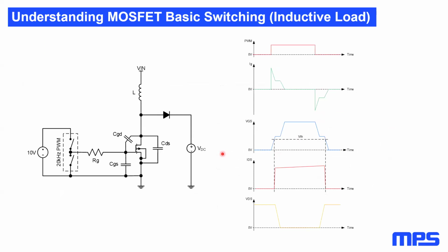The switching performance of the MOSFET transistor is determined by how quickly the voltages can change across its parasitic capacitors. Two of these capacitors, the CGS and the CGD capacitor, correspond to the actual geometry of the device, while the CDS capacitor is the capacitance of the base collector diode of the parasitic bipolar transistor, the so-called body diode.